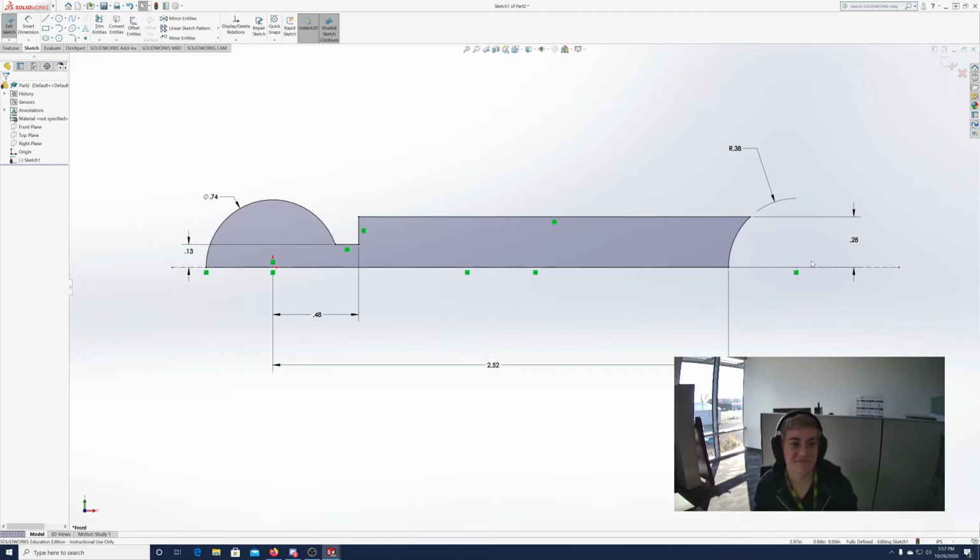So I think sometimes, if you have an extra relation in there that just got added in when you were drawing it, then it'll end up not working for you. And sometimes you don't ever really figure out exactly what it was, but you kind of have to just play around until you find the right combination of dimensions and relations.